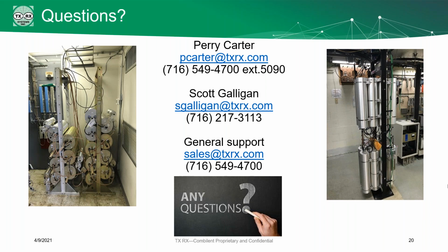Okay, thank you, Jim. And another question, how do you handle high power for 3/4 wave cavities where the center conductor gets hot? Well, for the most part, if the center conductor is getting hot, I think I'd want to look and make sure that the center conductor and all the connections are proper, because it almost seems like something might be giving some reflected power to increase that heat.